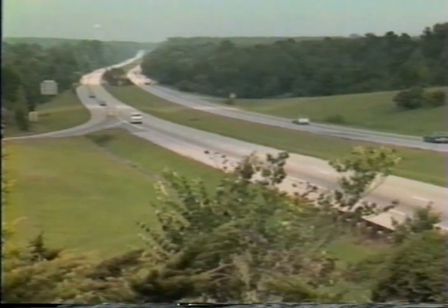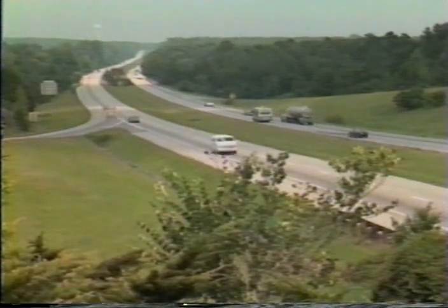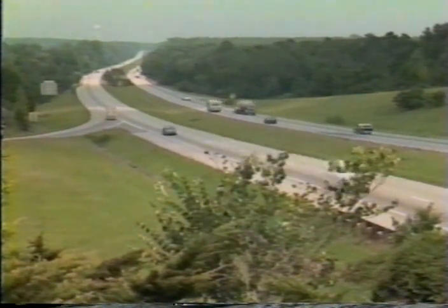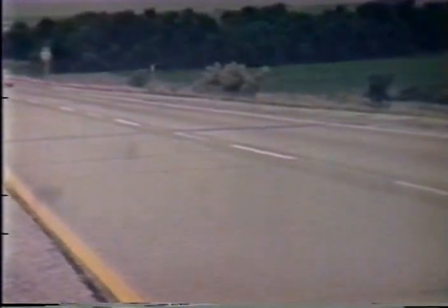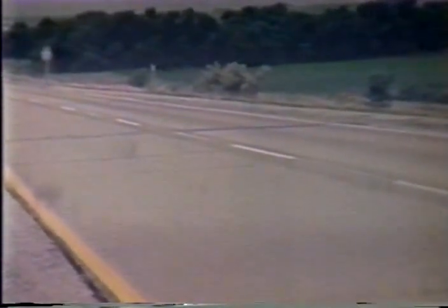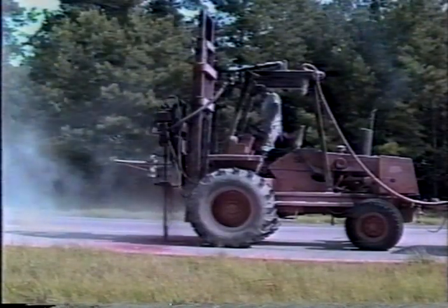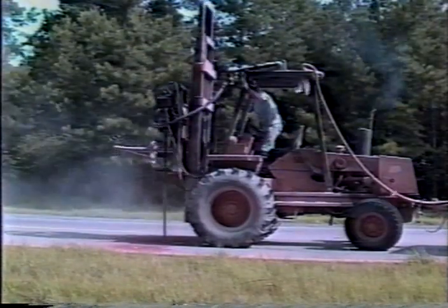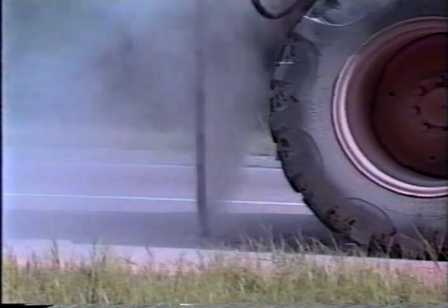Equally important is the condition of the original pavement, because it remains an integral part of the pavement structure after overlaying. For example, pavements with significant deterioration due to durability problems such as D-cracking or reactive aggregate are not good candidates for bonded concrete overlays. For the overlay to perform well, all distresses in the base pavement that would reflect through the overlay or impede bonding have to be corrected.